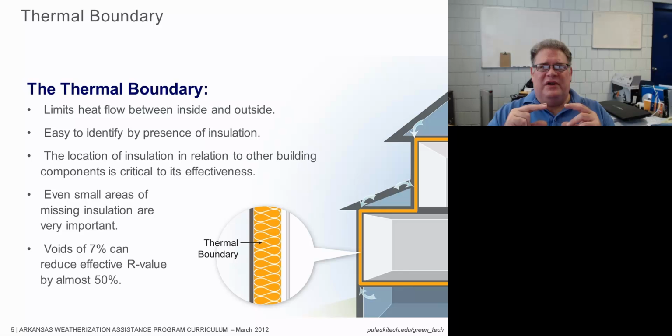So when you have small missing voids, they don't seem like they're very much, but they really affect the entire system. And this goes back to house as a system. They really affect the way the attic performs. It's going to bring it down by about 50%. So that's not a good thing.